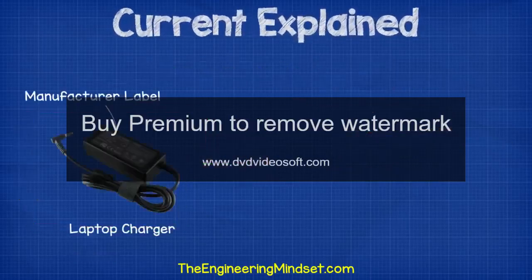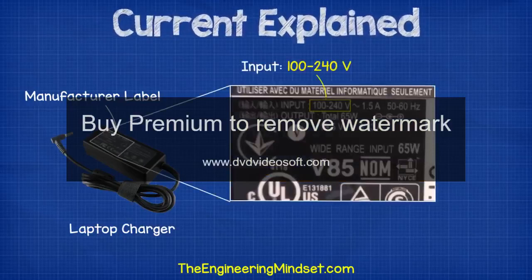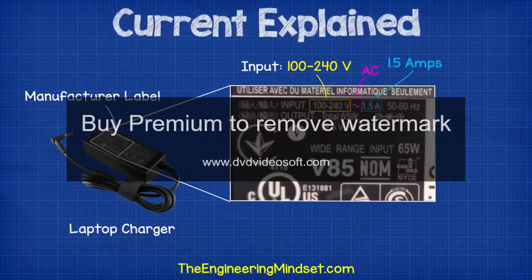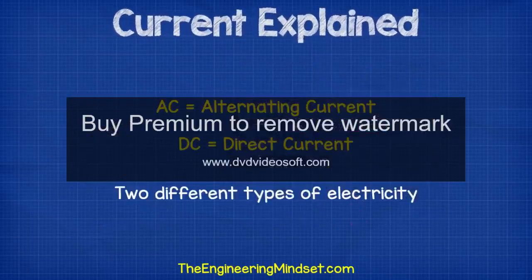If you look on the plugs of your electrical devices, you should find labels from the manufacturers which tell you what the product is designed to handle. For example, this laptop charger tells us that for the device to work, it needs an input of between 100 and 240 volts and 1.5 amps of AC or alternating current. The charger will then convert this to give an output of 19.5 volts and 3.3 amps of DC or direct current. AC and DC are different types of electricity.